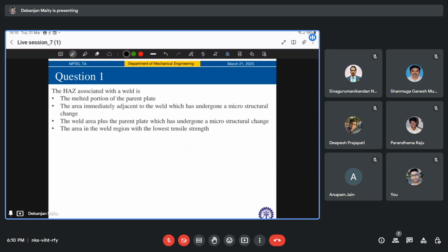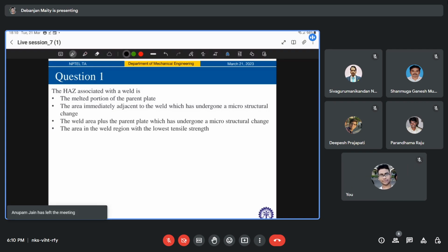Now, in fusion welding, the heat affected zone is an area of a base material, either a metal or a thermoplastic, whatever you are welding, which is not melted but has had its microstructure and properties altered by welding. These are heat sensitive regions, right? The heat from the welding process and subsequent recooling can cause this change, from the weld interface to the termination of the sensitizing temperature in the base metal.